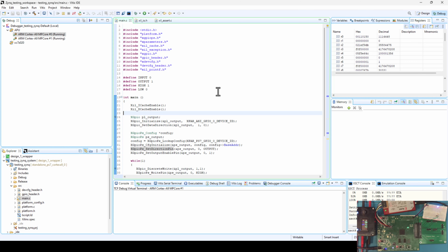Again, what I narrowed it down to is the configuration back in Vivado for the processing system. Oh, and by the way, I am still running the 25 megahertz oscillator into the processing system. And at a later point, hopefully later this week when I get that part in, I'll bump that up to 33.33. But I'm running 25 for now because I have not received those parts yet.